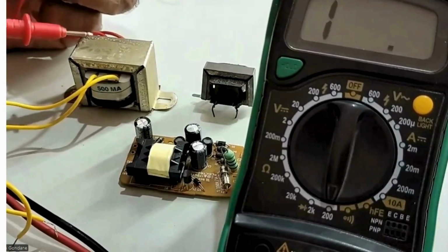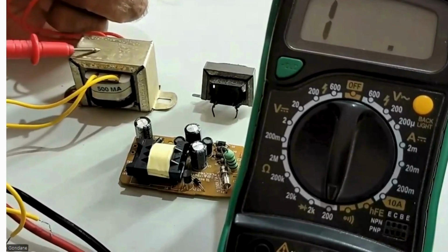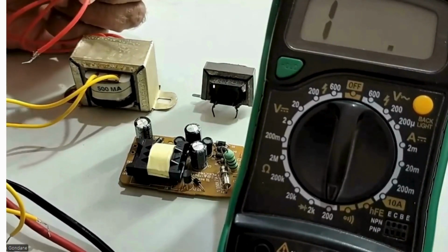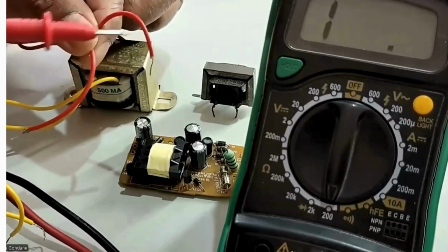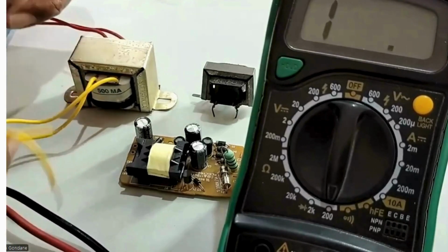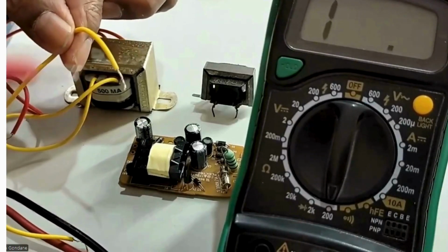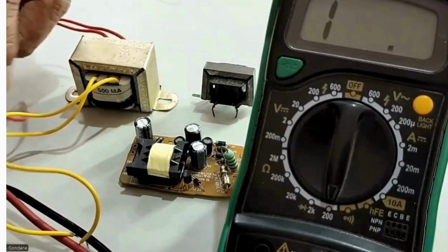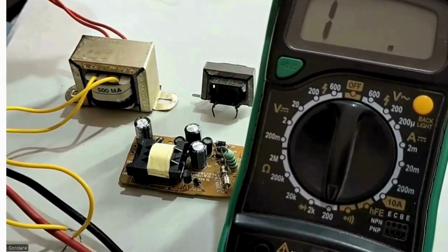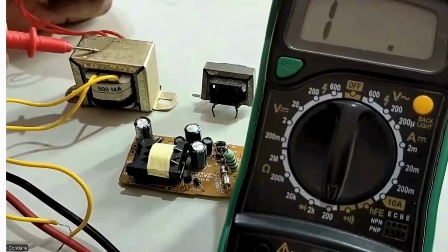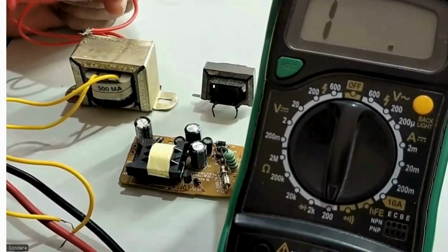Please remember, this is a step-down transformer, because the maximum of electronic circuits use step-down transformers. Where you get more resistance, here we got more resistance, 1.8K, this is the primary, and this is the secondary. This is step-down, so the resistance on the secondary side will be less. So my transformer is working because I've got resistance on both sides. Number 2, I came to know which one is primary and which one is secondary. Number 3, I have checked that my transformer is a step-down transformer.